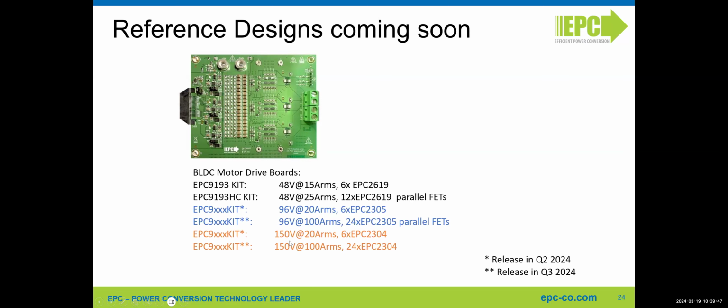And then we are also working on a 150 volt operation with EPC2304. EPC2304 is our PQFN 200 volt device, which is currently 5 milliohm, if I'm not wrong. And we will be releasing the single switch version, single device per switch, and also 4 devices per switch.